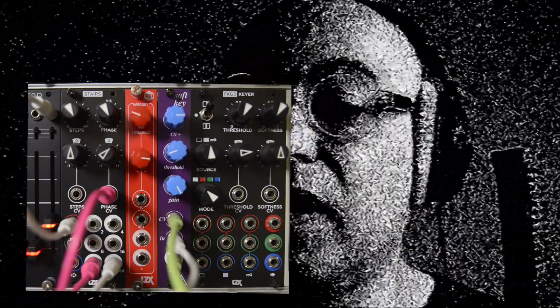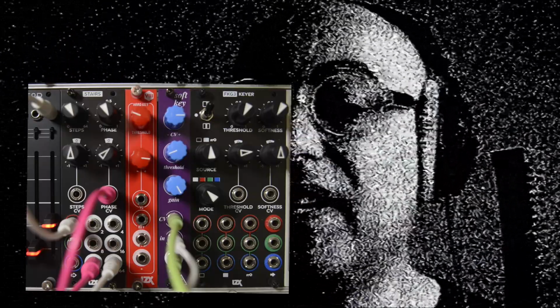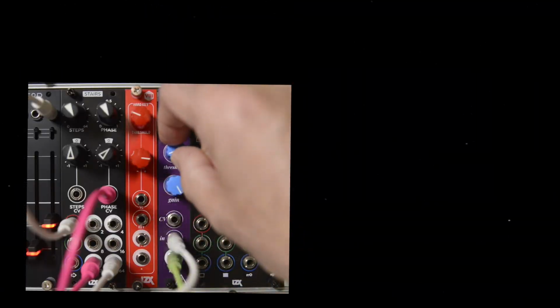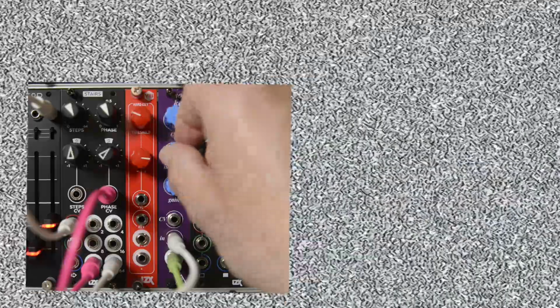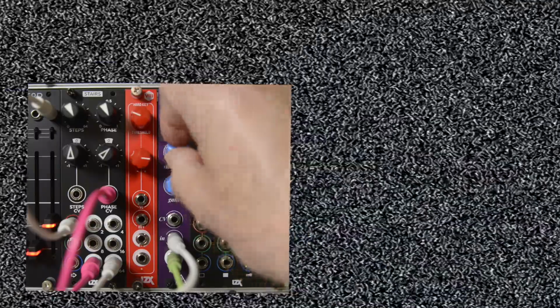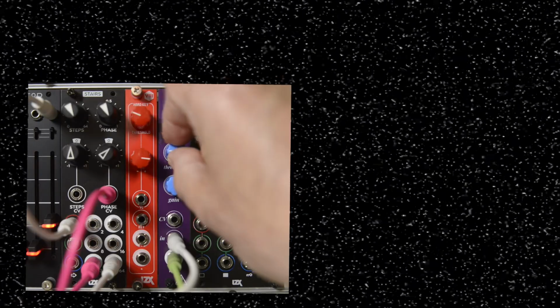I'll remove this camera input from the keyer's threshold CV control so that we can see the noise itself and how the keyer threshold affects it. As we can see here, the keyer's threshold affects how much of the bright, higher voltages are allowed through, which also changes the density and the noise pattern. This soft keyer allows varying voltages between 0 volts and 1 volt through.